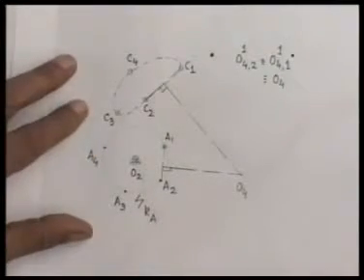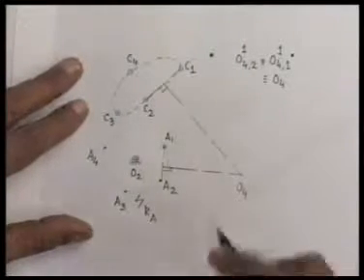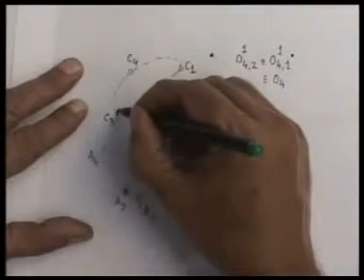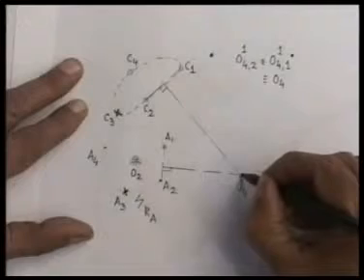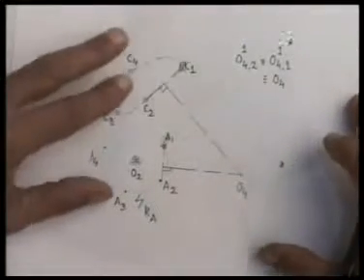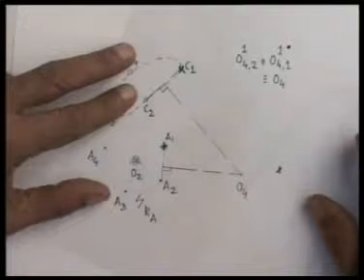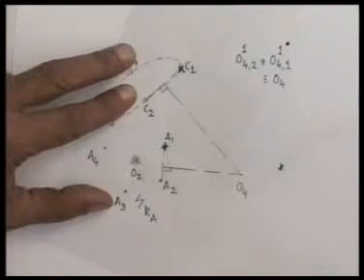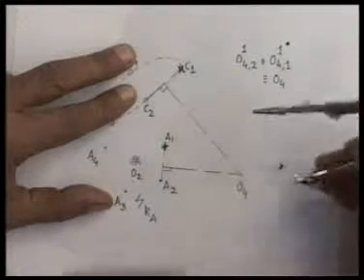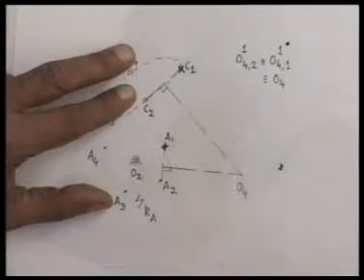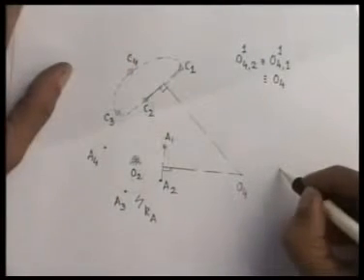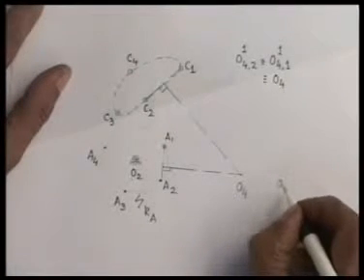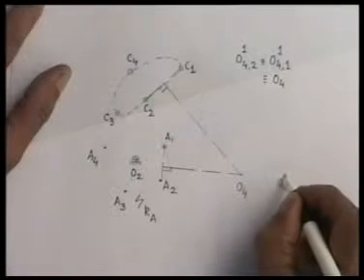Next, to get the inverted position corresponding to the third and fourth configurations, we go as usual: A3, C3, O4. Then A3 coincides with A1, C3 coincides with C1, and wherever O4 goes, that I call O431. So I can pierce my tracing paper and mark that point on the drawing sheet, which is O431.